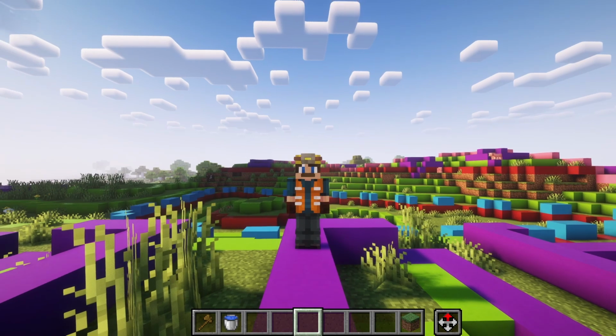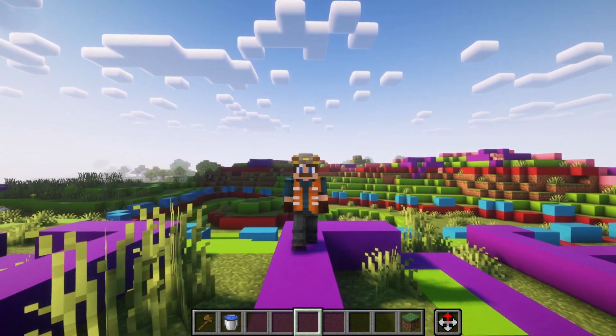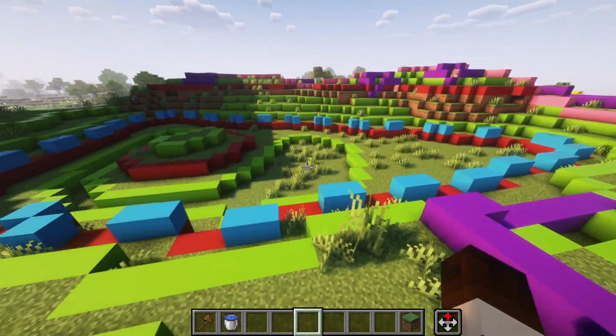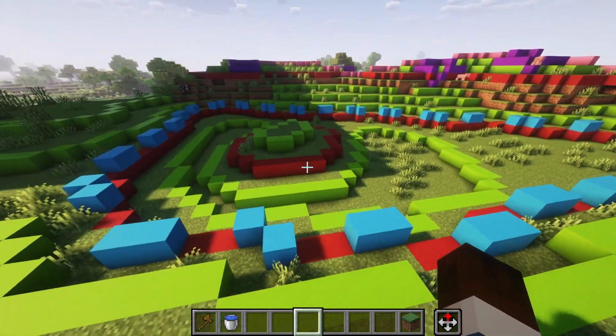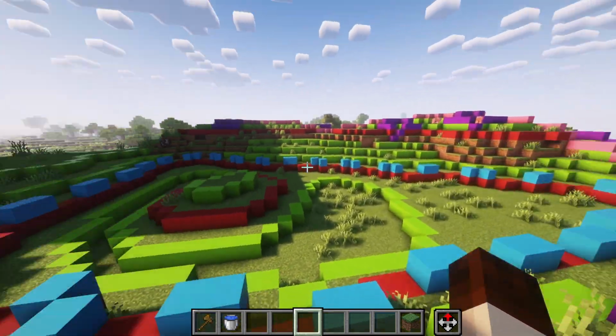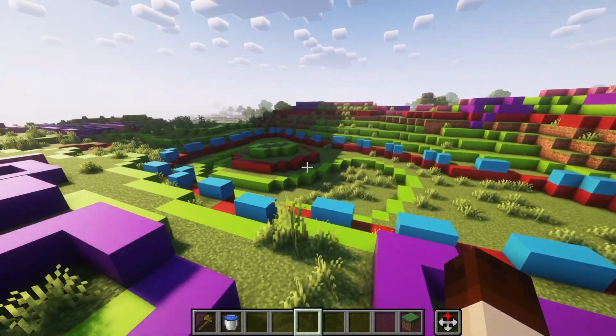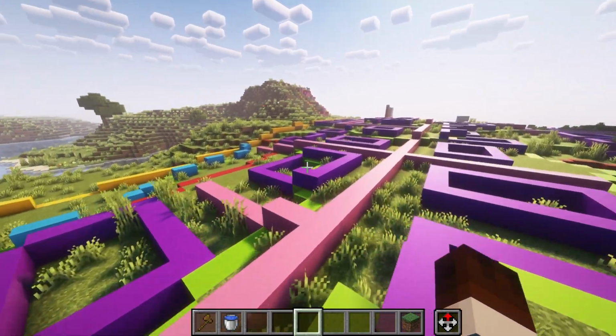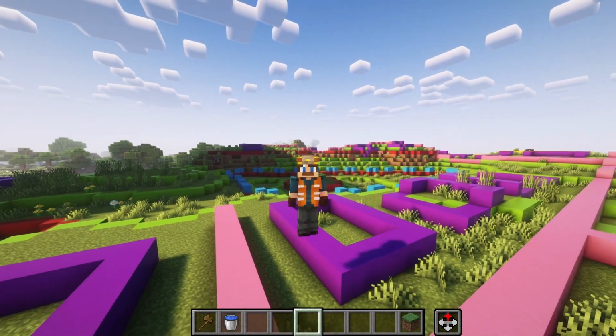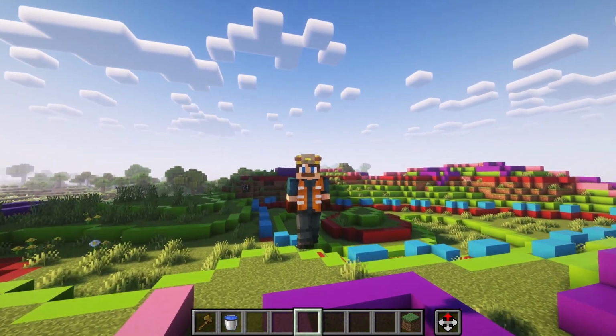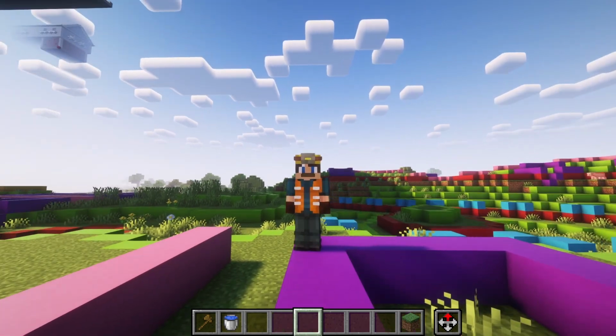Now, sometimes this is up to the jurisdictional agency whether you use retention or detention, but in the case that either is an option, it comes down to the developer, whether or not they want to have a standing body of water for the aesthetic appeal, or if they just want to have a grass swale or some sort of soft, dry bottom basin. That is totally up to their discretion. But in both situations, they need to make sure that it can maintain the 100-year storm event to prevent destruction.